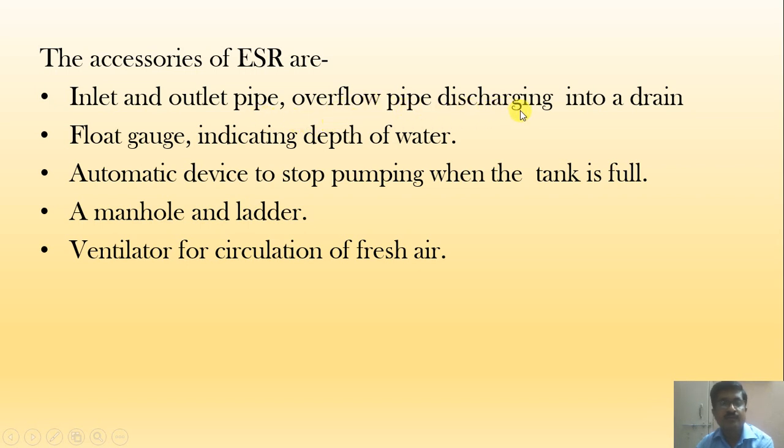An overflow pipe discharging into the drain, a float gauge indicating the depth of the water, an automatic device to stop pumping when the tank is full, a manhole and ladder, and a ventilator for the circulation of fresh air. Here also the float gauges may be provided with an automated system.